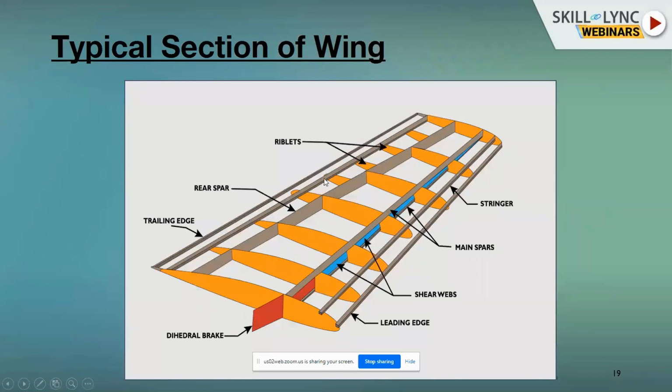These two spars, front and rear, are two beefy structures in the wing. Without them, the weight of the wing is like 50%; these two spars carry the 50%, excluding engines, which are beefier than anything else. That is how it is designed. Then you have ribs, which I mentioned earlier.